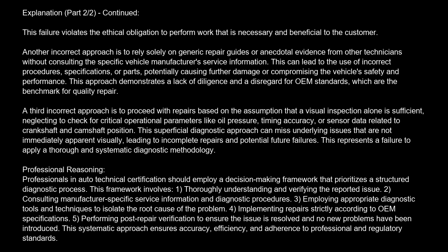for quality repair. A third incorrect approach is to proceed with repairs based on the assumption that a visual inspection alone is sufficient, neglecting to check for critical operational parameters like oil pressure, timing accuracy, or sensor data related to crankshaft and camshaft position. This superficial diagnostic approach can miss underlying issues that are not immediately apparent visually, leading to incomplete repairs and potential future failures. This represents a failure to apply a thorough and systematic diagnostic methodology.